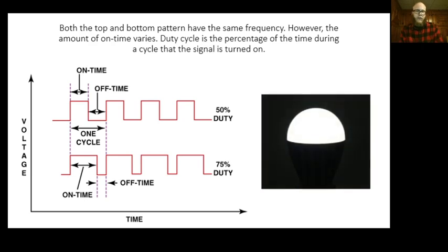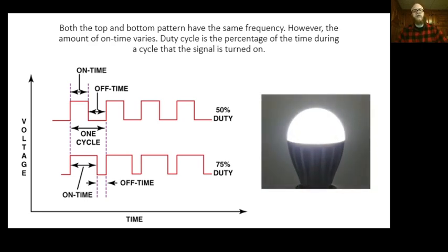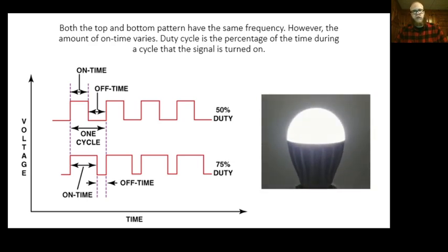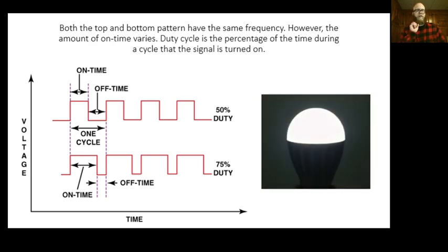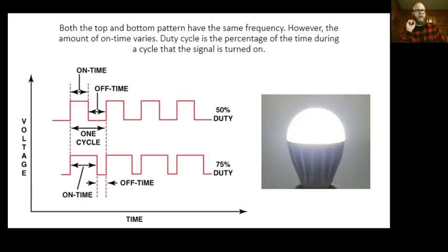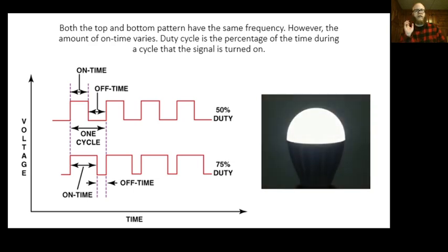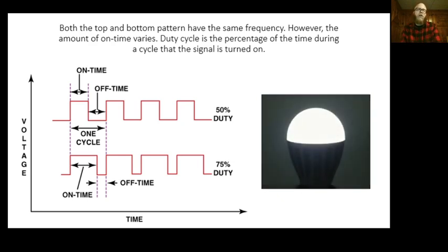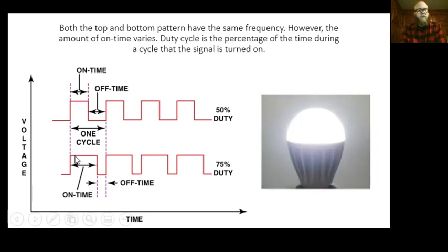And then the last topic I want to talk about is pulse width, which is often referred to when dealing with engine performance, where the pulse width of our fuel injector is 1 millisecond, so 0.001 seconds, while the vehicle's just sitting there idling. There's no consistent hertz rate, right? The engine's going to change speeds all the time, so the cycles are going to change with the speed of the engine. So what they care about is how long the fuel injector is on for. That's pulse width. How much time was it on for?